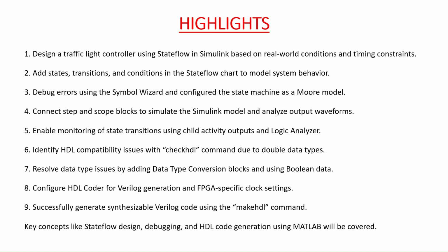Then we will configure the HDL coder for Verilog generation and FPGA specific clock settings. The last step will be to successfully generate the synthesizable Verilog code using the makehdl command. So this video will cover the key concepts like Stateflow design in MATLAB, debugging the errors and HDL code generation.